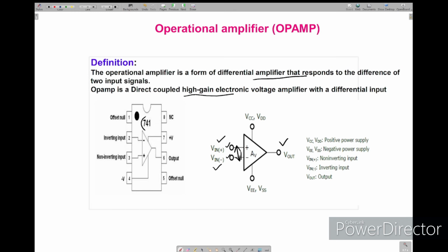In the block diagram we'll see how we can achieve this high gain, and by using which amplifier. If you see here, this is the 8-pin IC configuration of the op amp. All pins are useful here. One is offset null, inverting, non-inverting, and this negative V is nothing but minus V saturation. This positive we'll call plus V sat. And the set of pins we mainly use are inverting, non-inverting, output, positive VSAT, and negative VSAT.